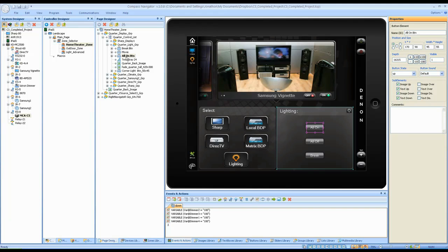And so instead of calling the scene command that was programmed in the Lutron system, because it was rather simple, just 2 dimmers in this job or 4 dimmers in the other jobs, we're just calling to those dimmers to manipulate the variable, much like we did in C3 Part 4, where we adjusted the variable. Therefore, the variable we'll explore here has the RS-232 commands and also manipulates the graphical user interface, the GUI property of those bulbs.